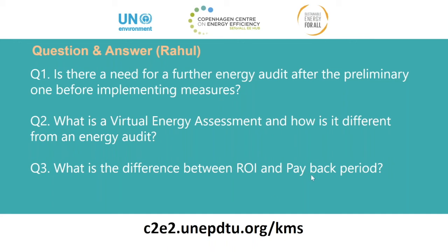Thank you, Begonia. As I have mentioned during the presentation also, it all depends on the purpose of getting an energy audit done. So the first question you need to ask is, why do you need to carry out an energy audit? As one of the examples which I have mentioned, if it is for these kind of, let's say, large scale municipal level projects, for data collection where the government wants to identify what is the potential in a particular sector, then a preliminary energy audit would be sufficient, by taking some sample industries in that sector and getting this done through the steps which I have mentioned earlier.